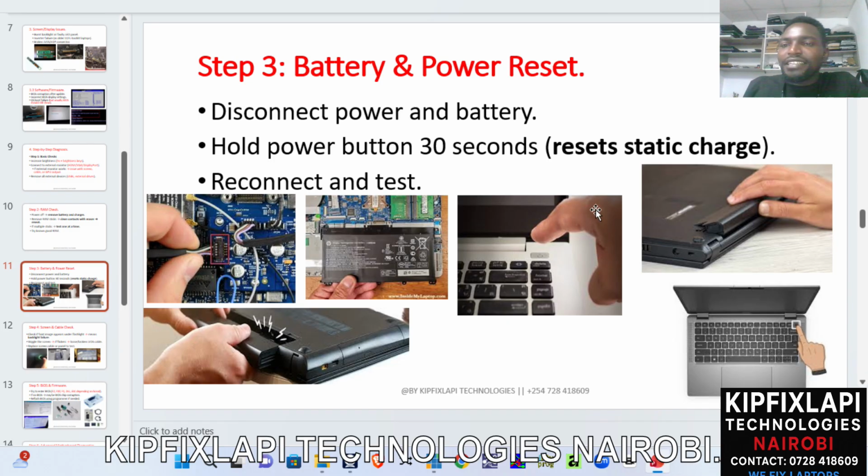Then after that, you put back the battery, connect back the battery. You can see the battery is being connected back. After you connect back the battery, now you press the power button again. Yes, at this point, most of the time you find that this solves the problem of no display. It resets the BIOS and your laptop will be back to life again.